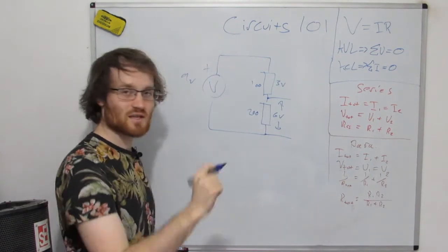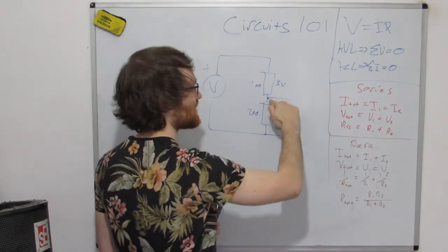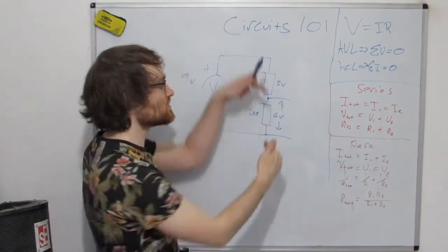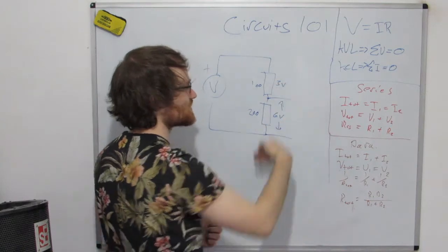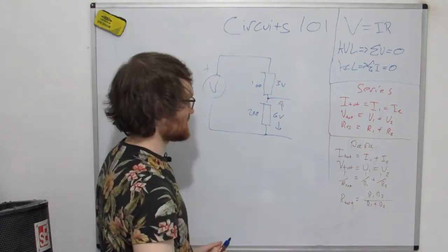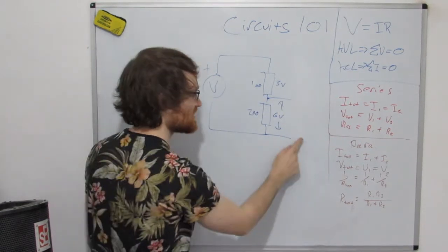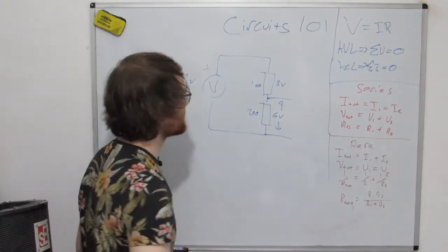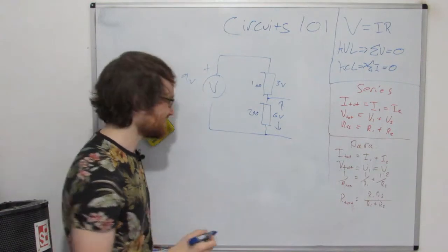And that's how a potentiometer works. You have the strip of resistive material and the wiper acts like this, and it's changing the ratios of these 2 resistors. So the overall resistance of the potentiometer never changes, only the ratio of resistance on either side of the wiper as it wipes around changes. And then if you take, this is the thing connected to the wiper and this is the thing connected to one side, and so depending on which side you take, you get a different voltage. And how does that relate to what we actually want to talk about, which is our filter?